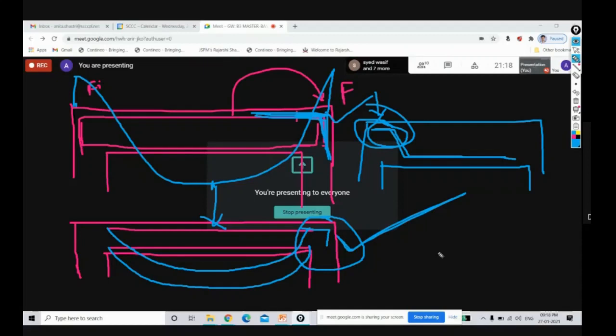Sir, at the junction it becomes critical, because the aggregate size will not go inside properly, it becomes critical, meaning honeycomb structure comes. If we provide lapping, proper vibration does not happen. Another thing, sir, whatever anchorage length we are providing, it will be 45D or 40D or 50D, but that much space is also not there. We cannot provide the beam reinforcement into the column, so generally we are not providing that much.